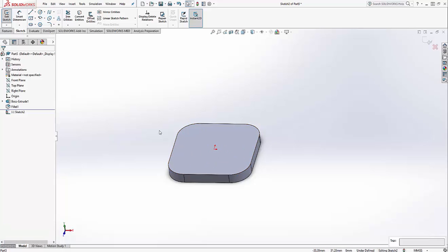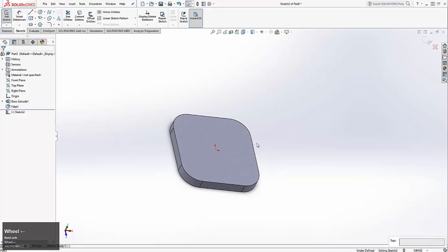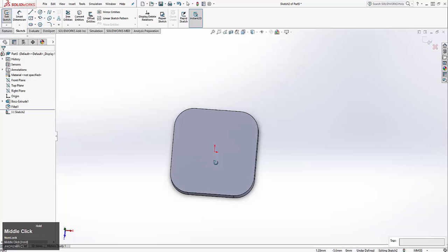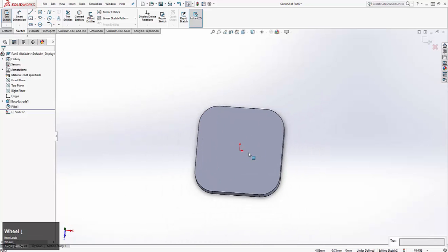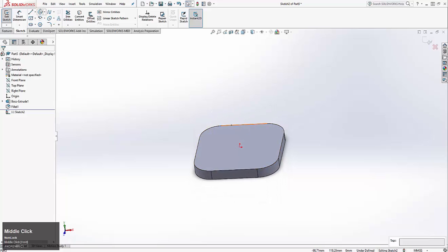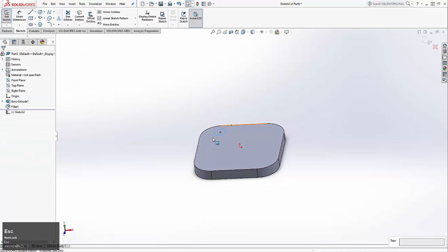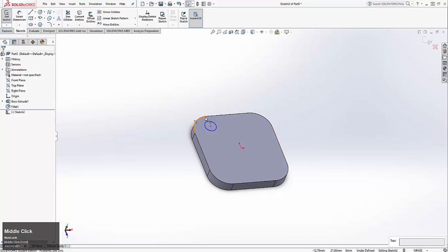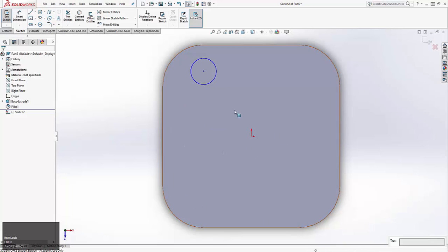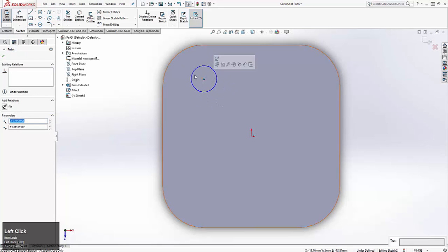So I can click on that face right there, and now we're over here in this weird view, and it's kind of hard to tell where we are relative to the sketch. So the perspective is a little bit messed up. Let me show you how messed up it is first, so you get an idea. If I draw a circle, that kind of doesn't really look like a circle because it's all over there and it's confusing. So what you can do is you can do Control and 8, and that's going to center your view around the normal, or just perpendicular to the surface you're working on. So it's very helpful with sketches.